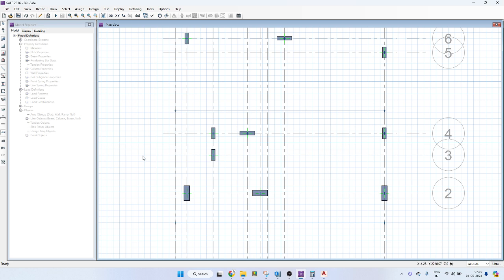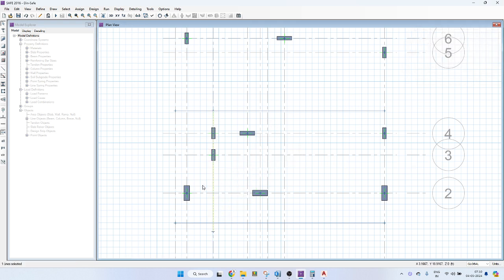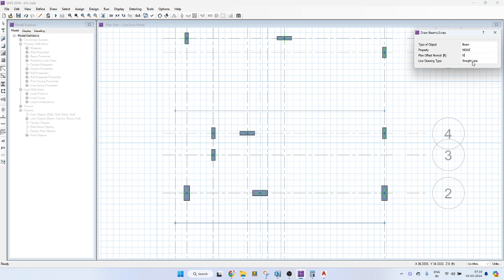And along the vertical, it is 5 feet 3 from this particular corner. See, for plan offset, whatever you're typing, ensure that that is being drawn. Oh, it is not able to understand 5 feet 3, so 5.25.